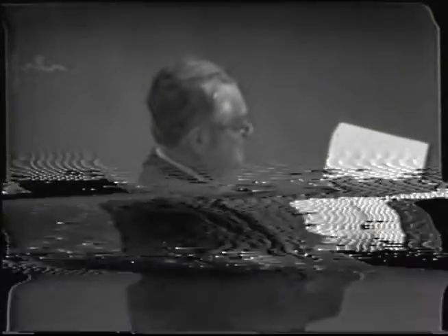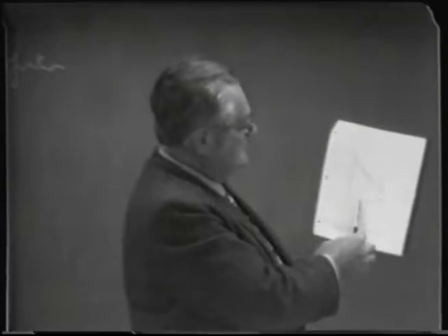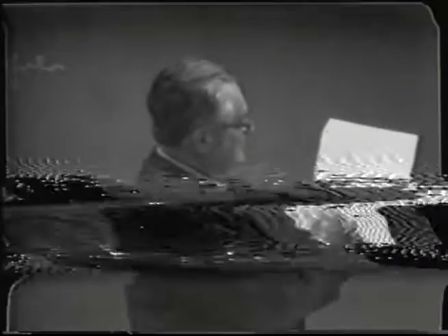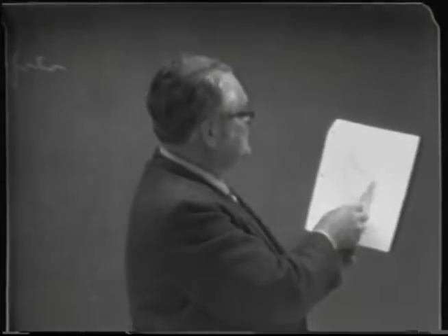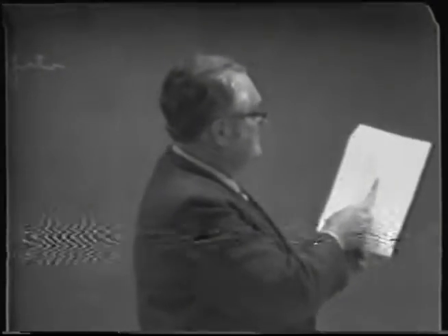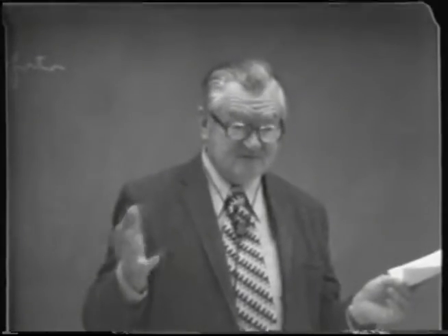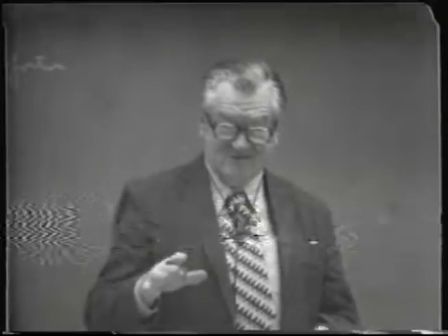As we decrease the ethyl alcohol content, we find a value at around 40%, maybe a little bit less, at which it crosses the ethyl alcohol curve. And so at that point, they would have, under equilibrium conditions, the same volatility. So this is roughly the point at which isoamyl alcohol would concentrate in the distilling column under completely equilibrium conditions.